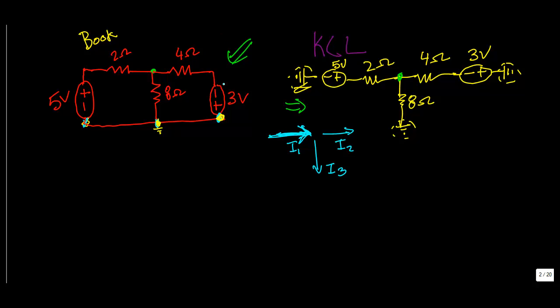So in this situation, we have a ground node here. This ground node actually shares this whole entire section here. So that means that this 3-volt source is tied to ground, the 5-volt source is tied to ground, and the other end of the 8 ohm resistor is tied to ground. So instead of doing a huge circle, the way that I draw is like so, just showing 3 separate grounds, which in reality do share ground.